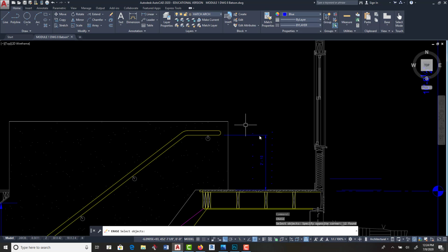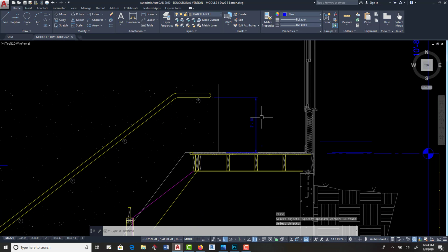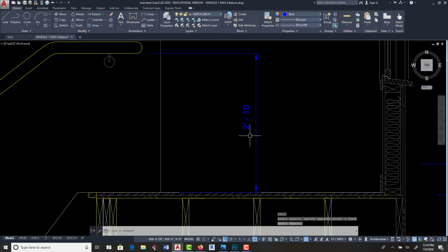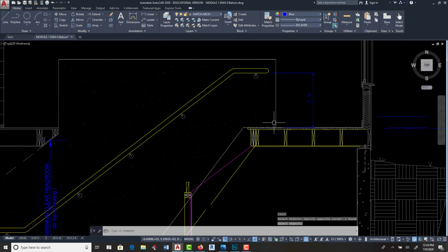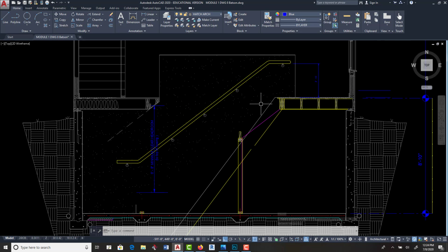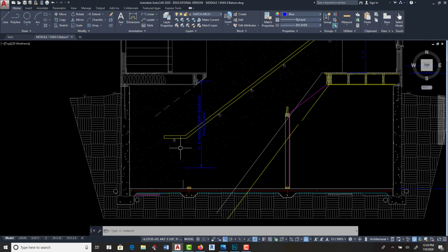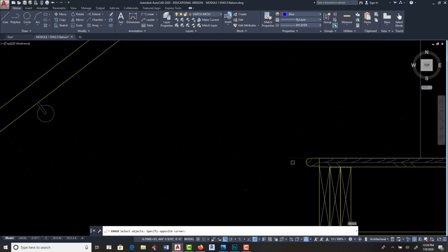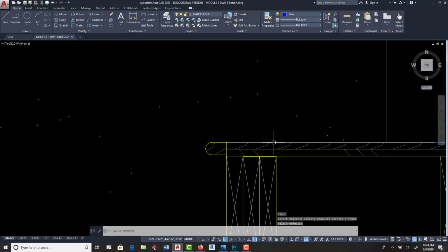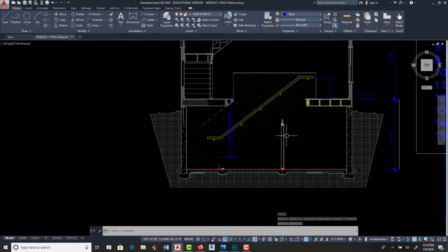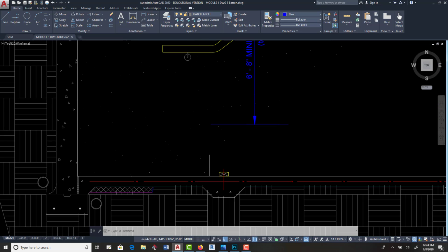So we want you to make sure the railing is 2 foot 10 at least, because the railing height goes from 34 to 38 inches. Okay, the height here has to be 6 foot. And your stringer has to be at least, you might want to do it 2 by 10, I mean 2 by 12. And of course, if it's larger, you can always splice two pieces together, and they can fix that.